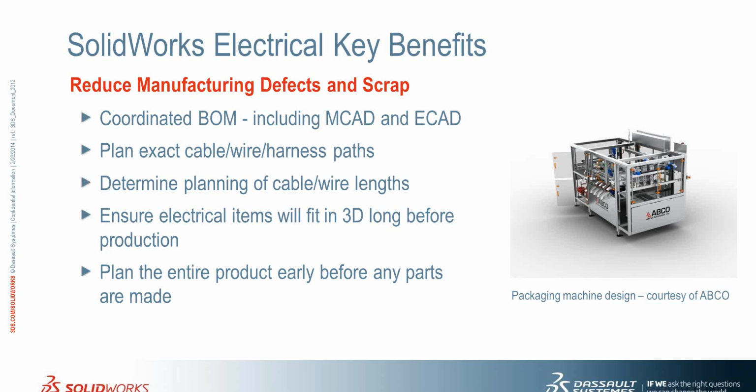So once you have the wiring in 3D, for sure, easily you can measure the wire length by automatically generating the wire harness table. So from here, it's easy for you to do planning. And if it's mass production, imagine every meter that you save is cost. Okay? And ensure electrical items will fit in 3D long before production.